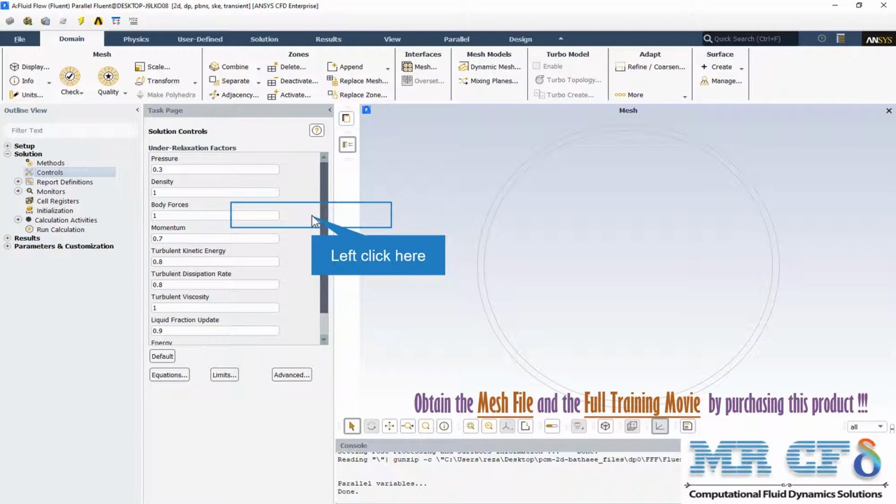A cautious approach is to save a data file before making any change to the under relaxation factors and to give the solution algorithm a few iterations to adjust to the new parameters. Typically, an increase in the under relaxation factors brings about a slight increase in the residuals, but these increases usually disappear as the solution progresses. If the residuals jump by a few orders of magnitude, you should consider halting the calculation and returning to the last good data file saved.